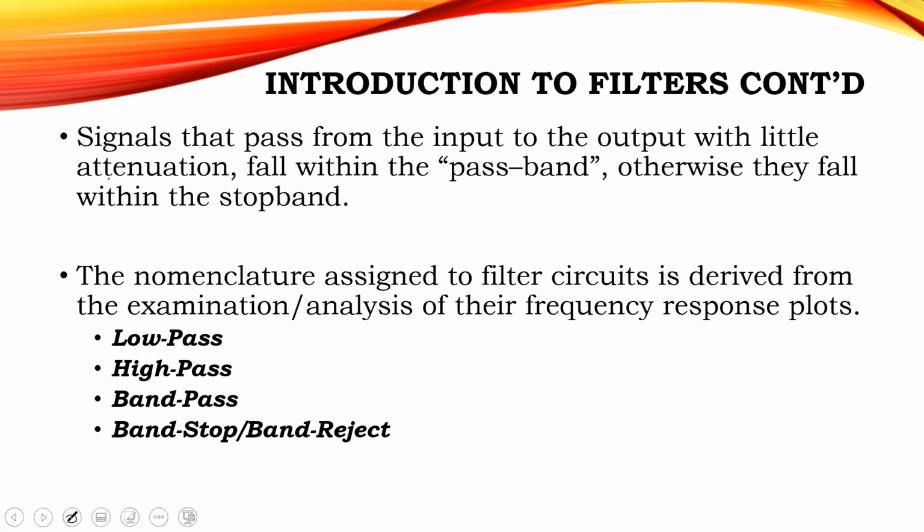So we can determine what the output would be like by virtue of where in the filter circuit we connect the particular reactive element. And I need you to keep that at the forefront of your mind. I may be using the same two elements within the circuit, but just by virtue of where I take the output, I can create a low pass or a high pass filter. All right?